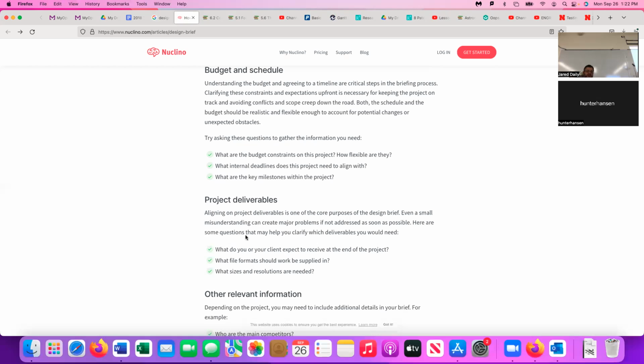For example, you have a specification for your project with the Arduino that you want to take data with voltage, and do we know the range of voltage yet? Well, maybe not. So we need to find that. They say, well, we want you to be able to measure voltage, but you can't just measure any voltage with any circuit. You have to know the range of voltages. How much voltage, how little voltage.